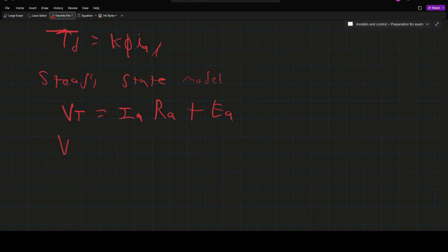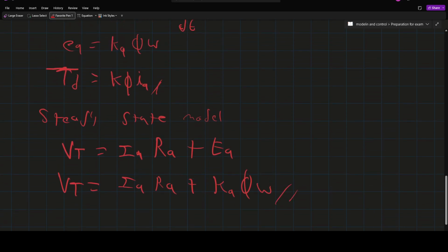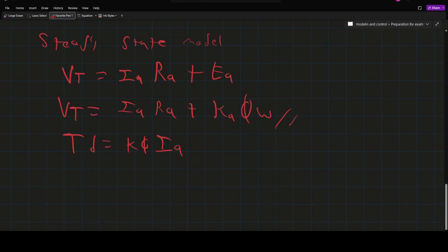And we know that EA is just our constant value Ka times phi times omega, our speed. For torque it's going to be the same: we're going to have K phi times Ia.